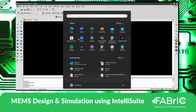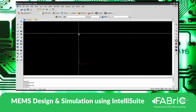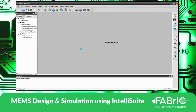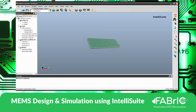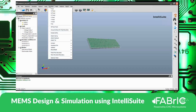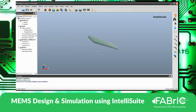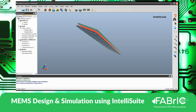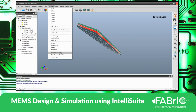Sorry, I think I'm using my laptop which is consuming a lot of memory. So here I select contact analysis, then face pair, face A. The bottom one is face A, which is deformable, and this is face B, and I would say it is rigid.